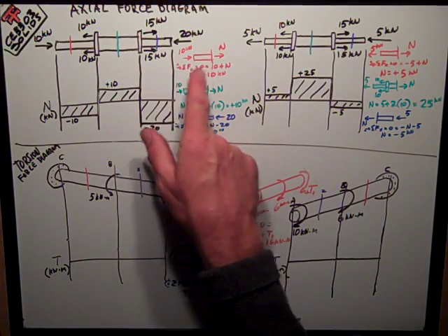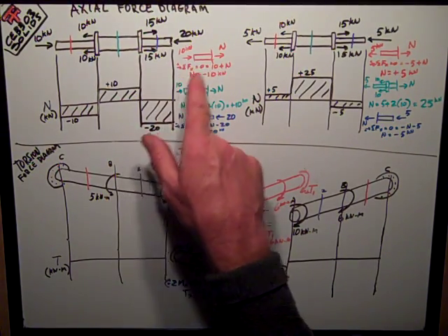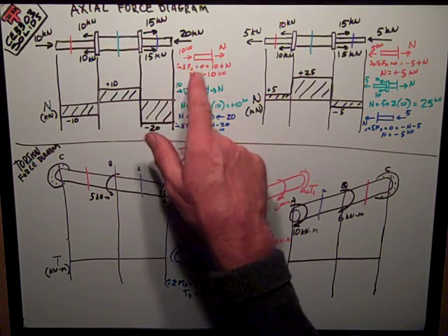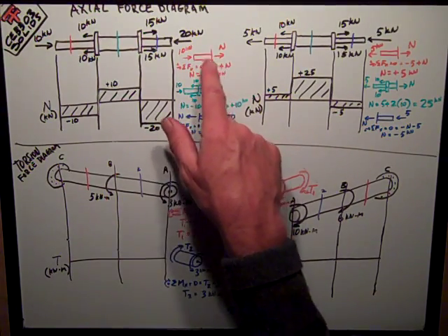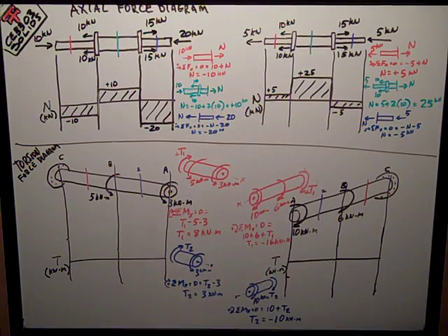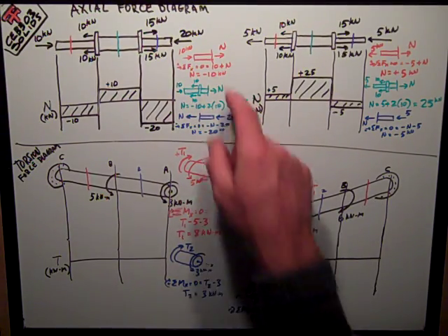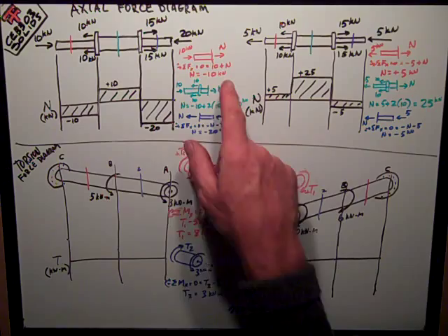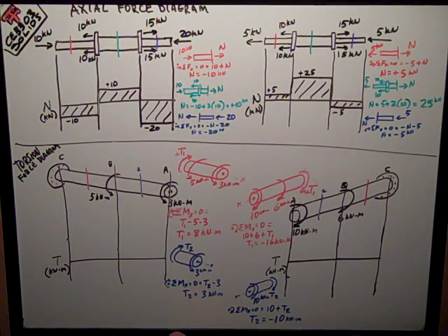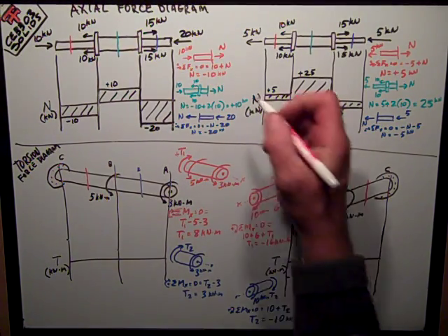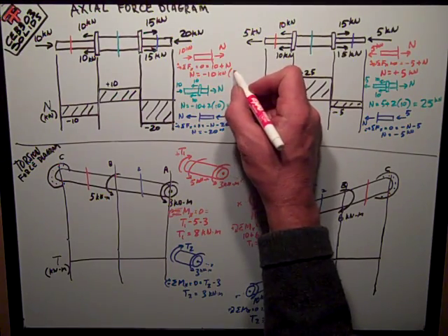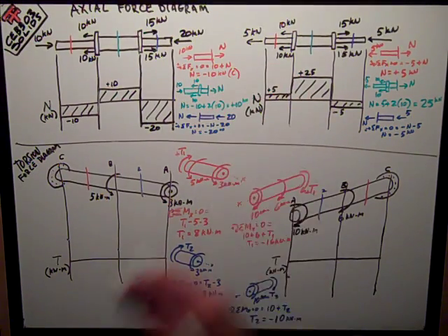So I've got 10 kilonewtons to the right. Sum of forces in the X is 0, 10 plus my internal force reaction N. Rearranging, I get N is equal to minus 10, so that's compression. Should show that on an answer like that and erase my negative sign.